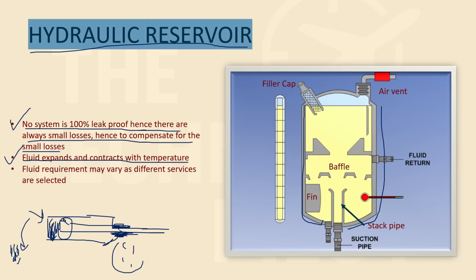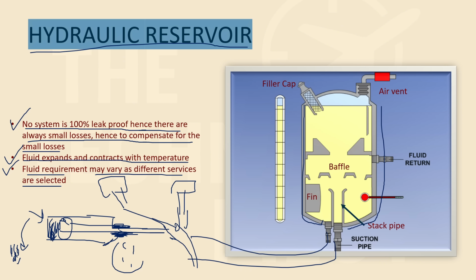And the third is that the fluid requirement may vary as different services are selected. Very common. If you are selecting, let's say, 4 or 5 different services together, the demand for hydraulic fluid will increase. So you will need a hydraulic reservoir to supply all of these services. These are the three reasons why it is needed.